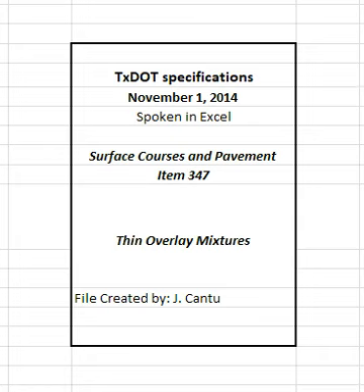4.9.2.2.1.1 Random sample. At the beginning of the project, the engineer will select random numbers for all production sublots. Determine sample locations in accordance with Tex-225-F. Take one sample for each sublot at the randomly selected location. The engineer will perform or witness the sampling of production sublots.